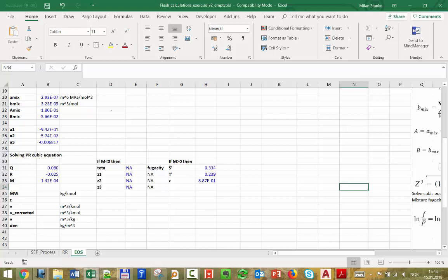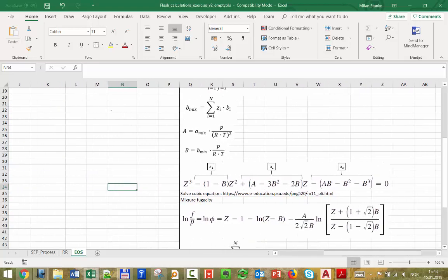is, you already forgot what we were doing, right? We took all of the things we have done just to find this equation to find Z. After I have Z, I have pressure and temperature. What am I looking for after all of that? Density. But I cannot calculate density directly. I calculate the molar specific volume.